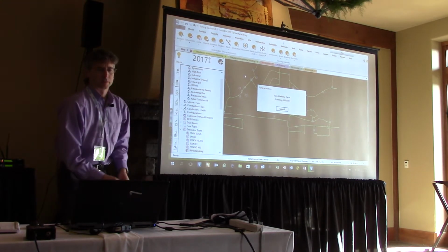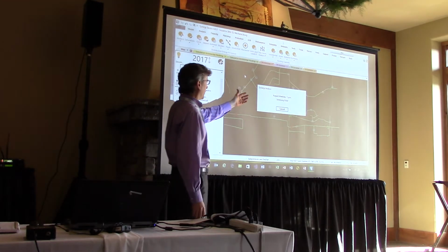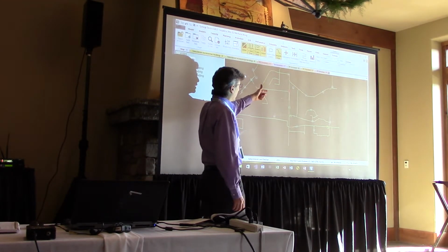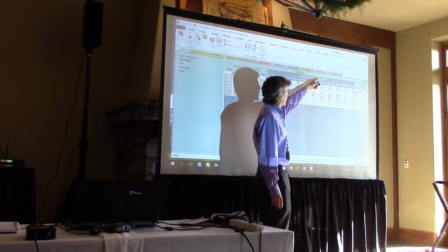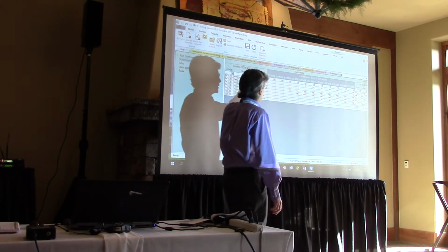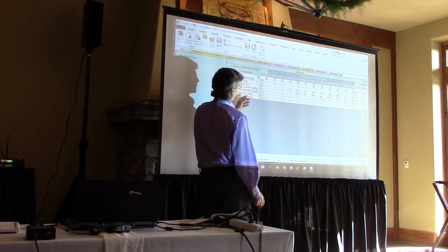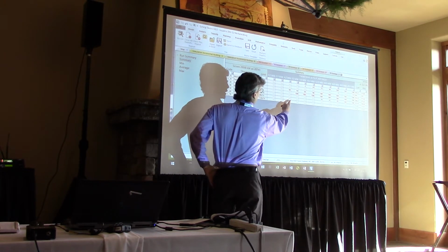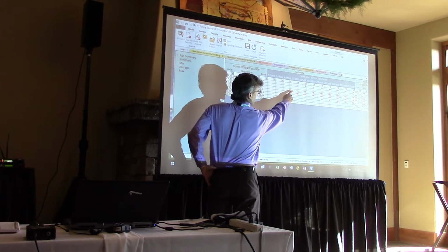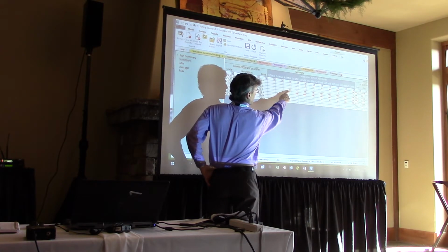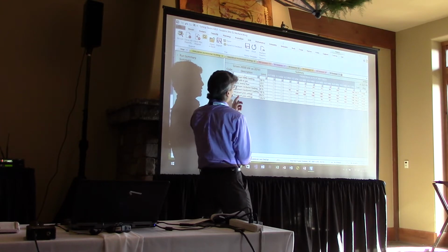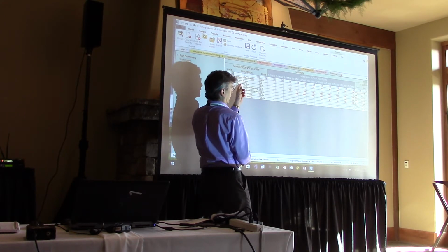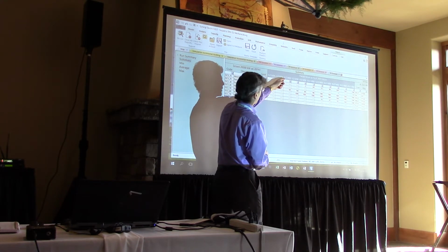There we go. This thing is running over four or five months, 24 hours a day. So this thing ran 2,600 hours. And now I look across here, and when we get to 4 megawatts, these numbers are percent. So 10% of the hours, about 260 hours, I'm going to hit a reverse flow violation at 4 megawatts.